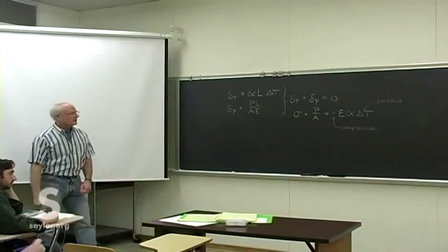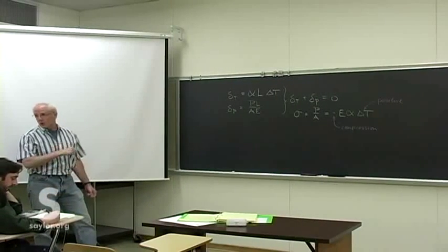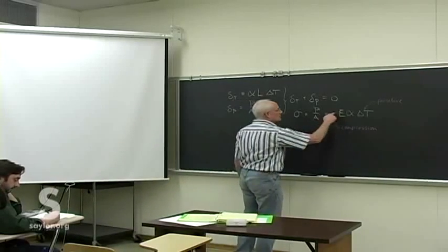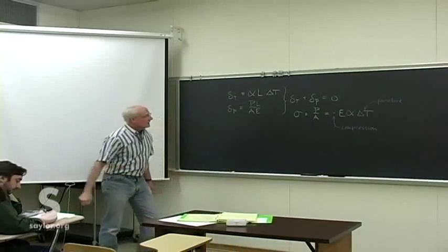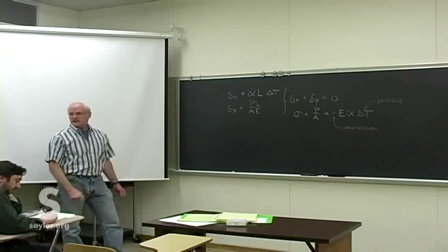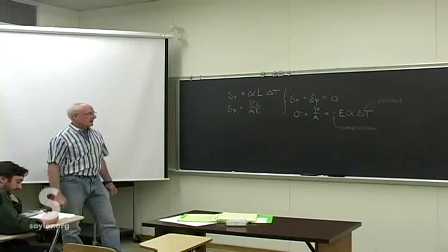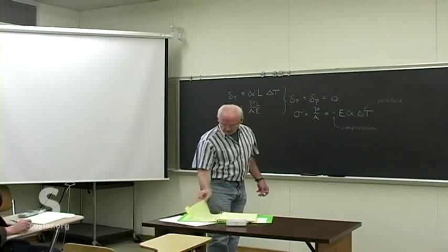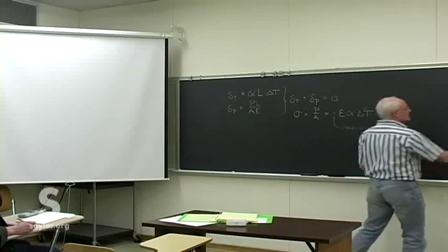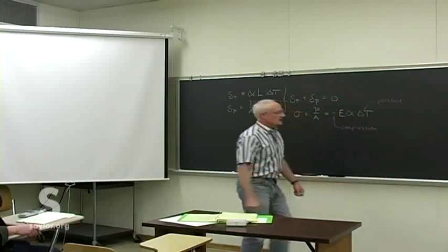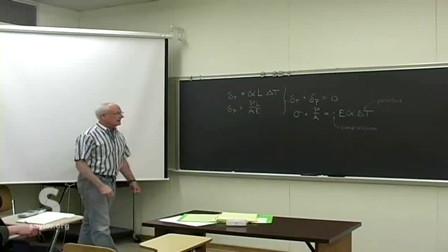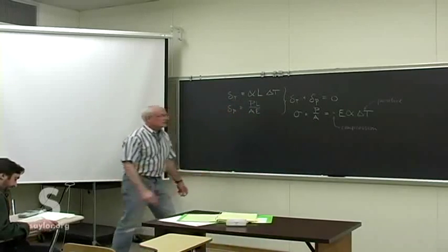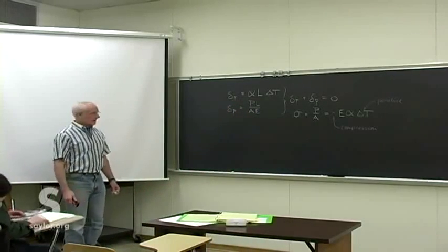So we can handle the fact that the piece may actually get colder. Delta T would be negative. If delta T is negative, the two cancel each other. We then have a positive stress because we're actually going to have to put the piece in tension to bring it back out to its original position. Just this picture essentially run backwards with a negative delta T. And in fact, we'll just do a couple problems now and then be done with it.